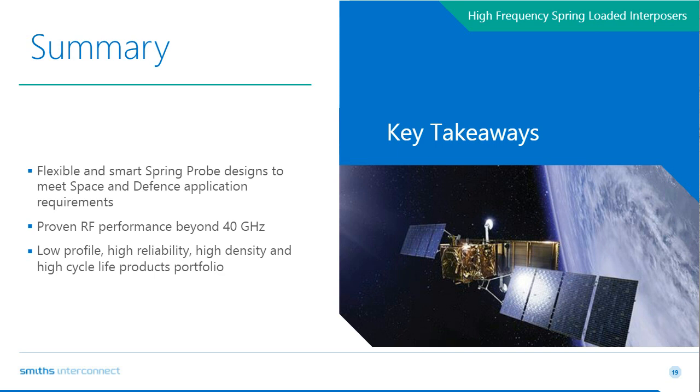Okay, sure. So one person asked, in terms of loss, how does a spring probe RF connection compare to other blind mate solutions like SMPs? So yeah, we've designed a lot of connector applications that utilize things like bullets and SMPs. The interconnects themselves, the interposers, can operate well into the 56 gigabit range in terms of RF.